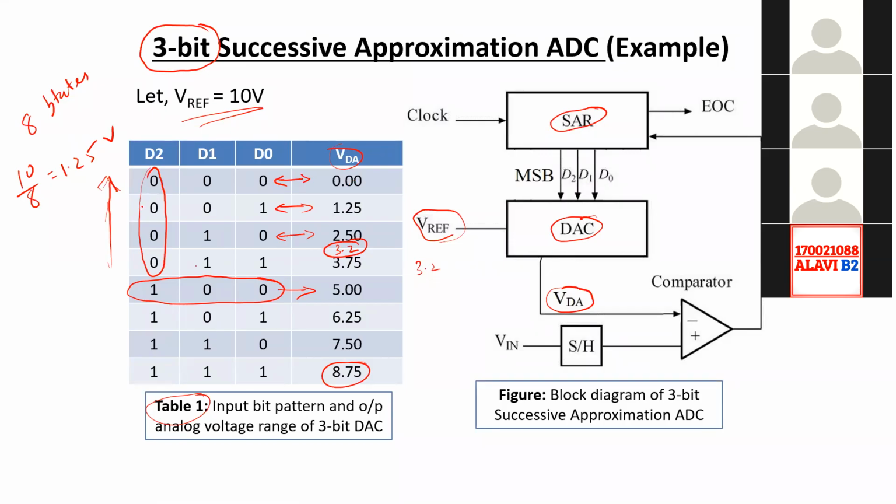But for 3-bit, it was relatively easier to do because there were only 8 quantizer states. Now, if you consider the 4-bit case, it would require 16 quantizer states. For 5-bit, it would require 32 states. For 6-bit, 64. So deriving a table of quantizer labels in this form would be a very time consuming job to do if this approach is followed.